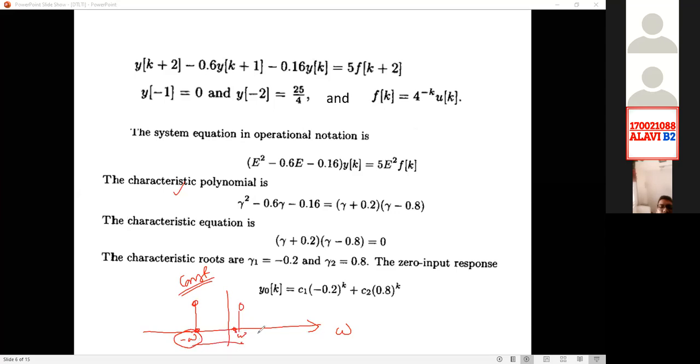The reason is that when we are using the complex form, these two would be needed in order to cancel the imaginary part of your solution. So the constants will appear as conjugate pairs. Half will be on the positive side, and that's why the spectrum will be symmetric with respect to the omega equal to 0 axis. I don't know to what extent you have explored it, but we will revisit it in great detail in this course also.